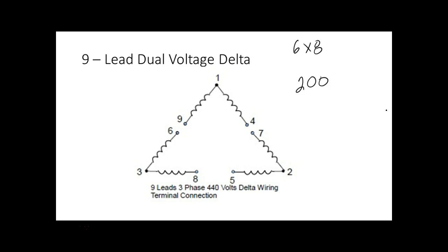You understand that? So what they did for a while was that they did what they call reduced voltage starters, where they would come in there, and when you started the motor, they would put less voltage on the motor. And that means if you put less voltage on the motor, it would create less torque. So a lot of your big motors, we don't want to put those things across the line, because when you start them up, they're going to pull a lot of current, but they're going to create a lot of torque. I've seen motors strip gearboxes out before, just trying to get them started. And then you turn all that horsepower loose.